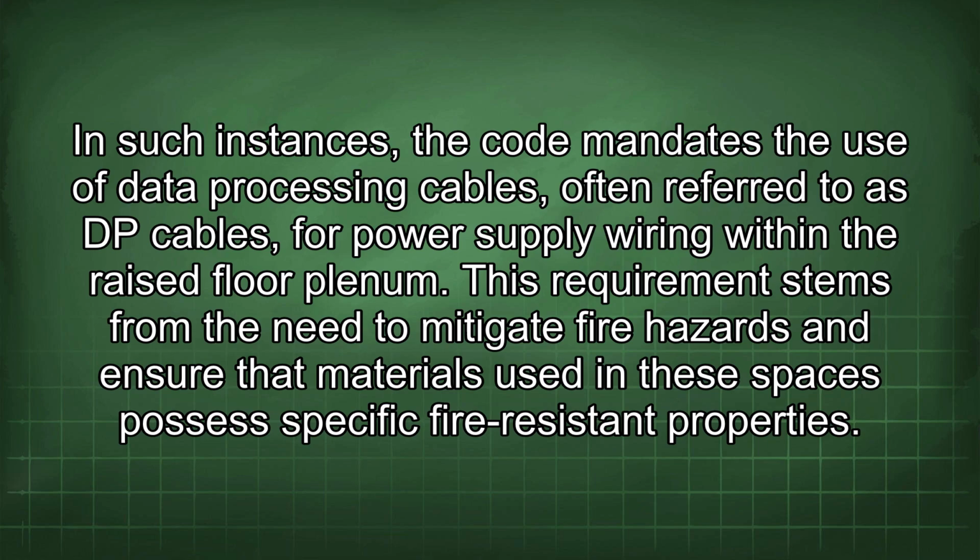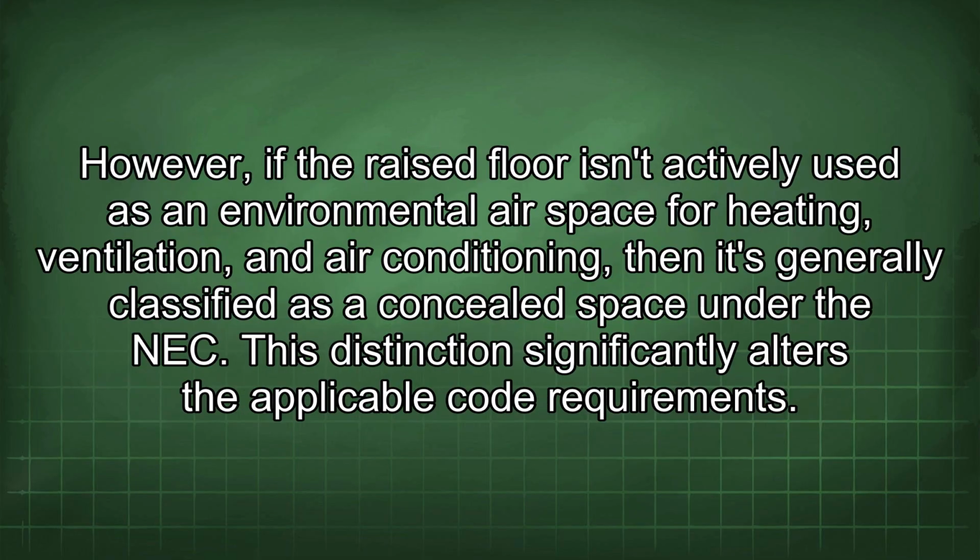This requirement stems from the need to mitigate fire hazards and ensure that materials used in these spaces possess specific fire-resistant properties. However, if the raised floor isn't actively used as an environmental airspace for heating, ventilation, and air conditioning, then it's generally classified as a concealed space under the NEC. This distinction significantly alters the applicable code requirements.